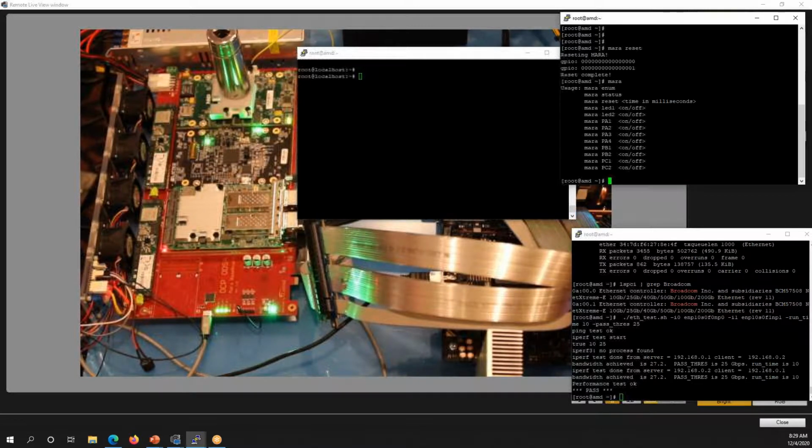Then you can look at the status, you can do a remote reset, you can control the LEDs, and you can also control the GPIOs by executing the command. So if you have hooked up one of your power pins to any of these GPIOs, you would be able to power cycle your system or your particular Pitchlet that you have developed without disturbing any other. Or you could execute a master reset, which will reset the entire board. Any kind of utility is possible.